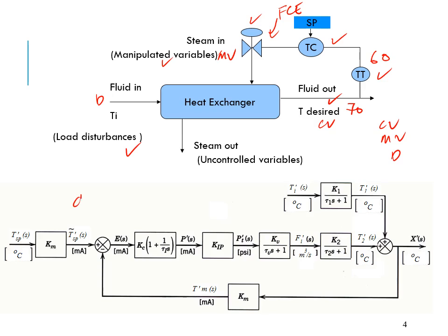This figure shows the closed loop of the feedback controller. Why do we call this a closed loop? Because any deviation from the set point is corrected by the use of the controller, as opposed to the open loop system, where human intervention is needed to take any corrective measure. So the closed loop and feedback controller is the most common type of controller used in industry.